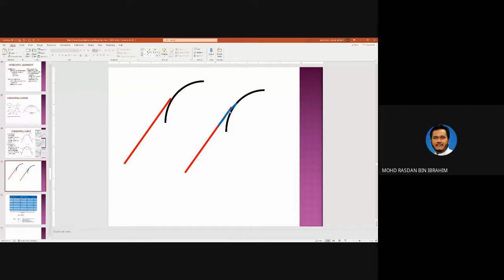So spiral transition curves are used where the radius of the curve is within a specific range. If it is too big, you don't need a transition curve. If it is too small, you do not need a transition curve. For large curves, it will seem to you that you are driving on a straight. The transition does not play any role anymore. With a 1 kilometer radius, you do not feel that you are actually driving on a curve.